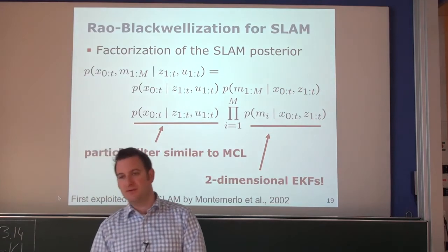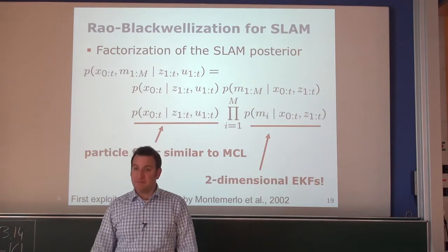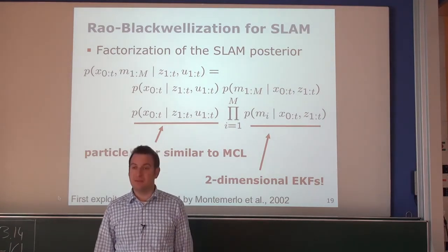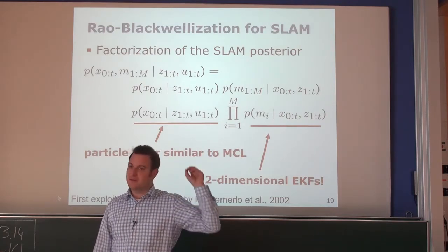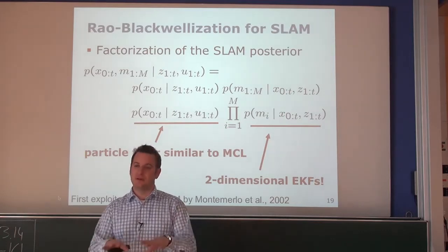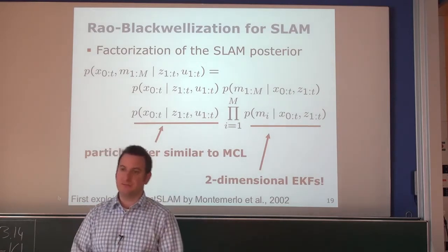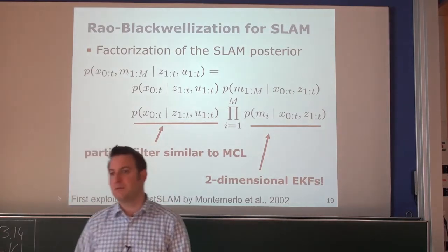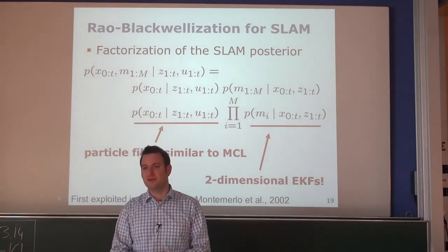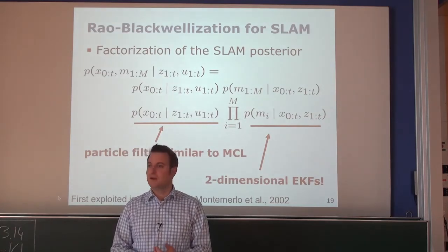But if you want to start, for example, in a GPS reference frame because you want to relate the robot's trajectory directly to a map and maybe exploit this map partially during the mapping process, and you have an initial distribution about where the robot is, you can use those samples to represent the start belief. You may need more samples in the beginning, depending on how large your initial uncertainty is. But most implementations start at 0, 0, 0. It's kind of an easy extension if you want to use an initial uncertainty. Any further questions?